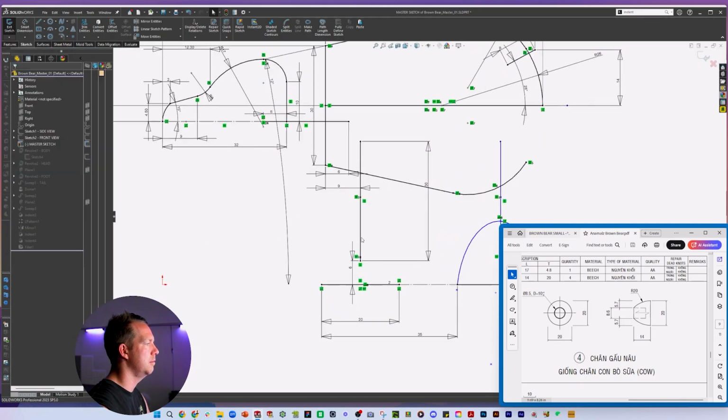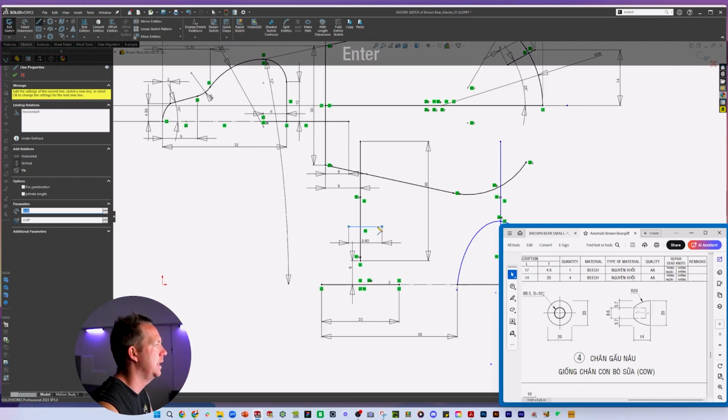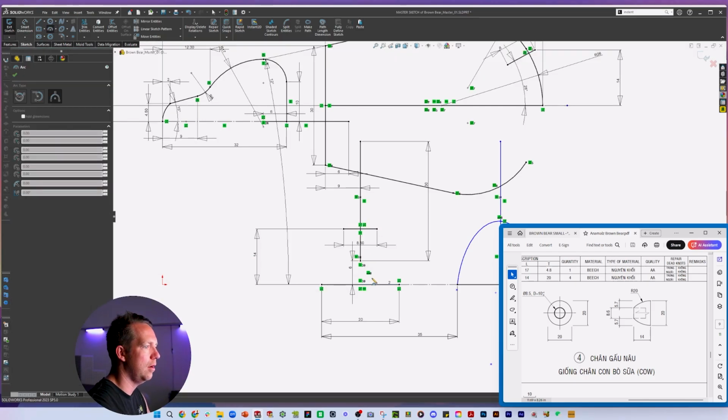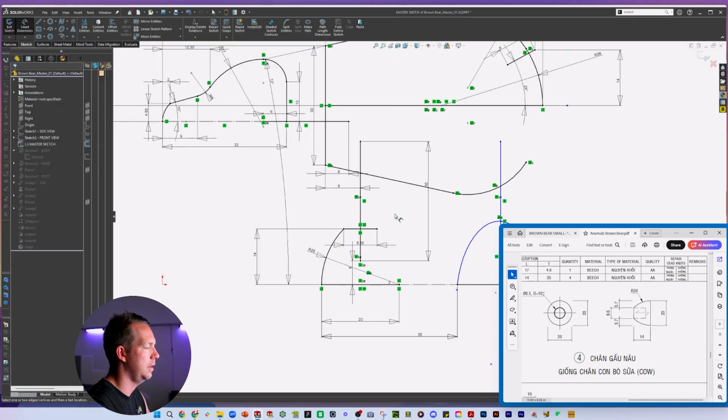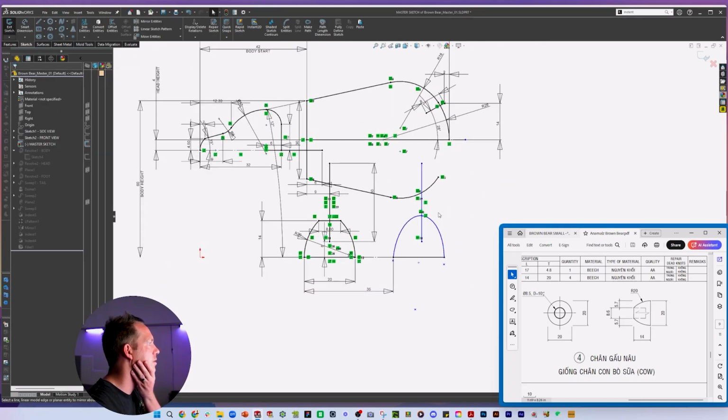I'm then going to put in my top, which has the hole as 8.6 in one drawing and 8.5 in the other. Let's use 8.6. The factory can always tweak it if they want to. It's got a height of 14. We were pretty close to that already. And a radius of 20 on the sides. That is pretty good. Let's mirror that back to here. And then should we update the back leg? Yeah, probably. The distance apart was 35 millimeters. So let's just remember that.